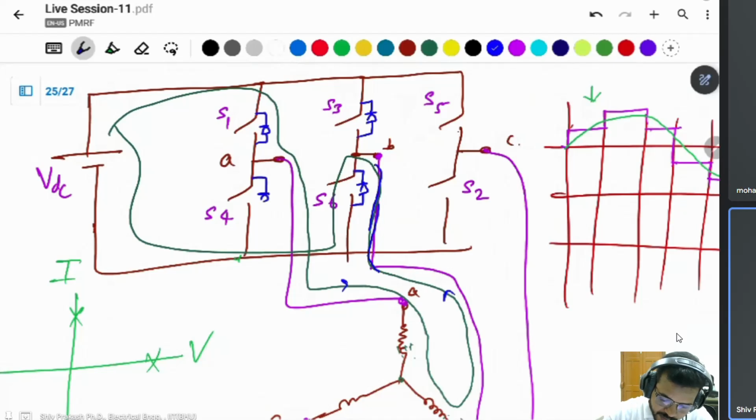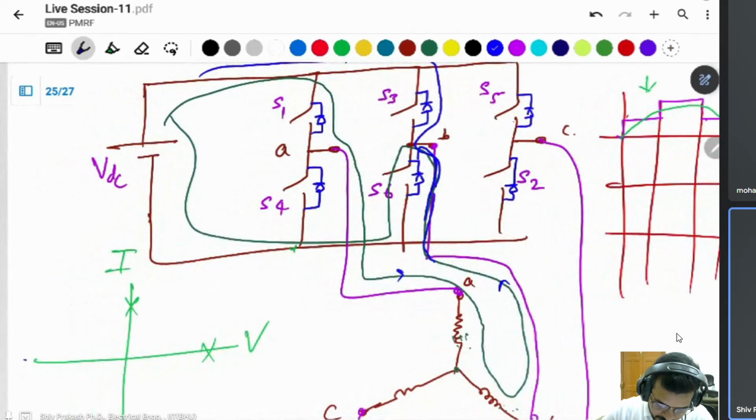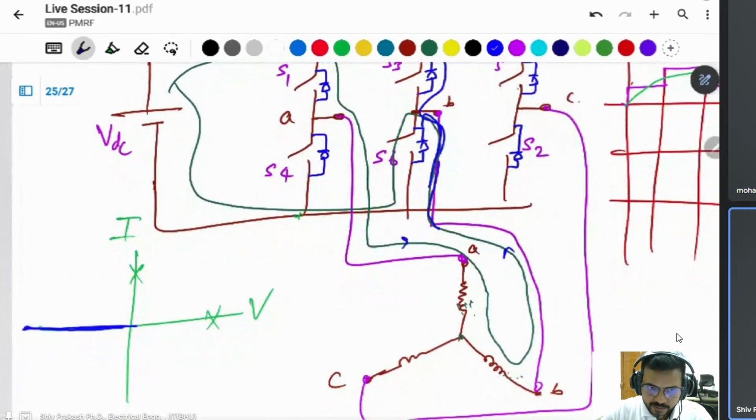Diode is required for this only. Then current will not flow directly here; the current is flowing from this path, making a circuit, and current is flowing back to the DC system. That's why there is no blocking capability in the opposite direction. The switch should not have blocking capability in reverse, because the current flow will be bidirectional and blocking will be single-sided, not both-sided.